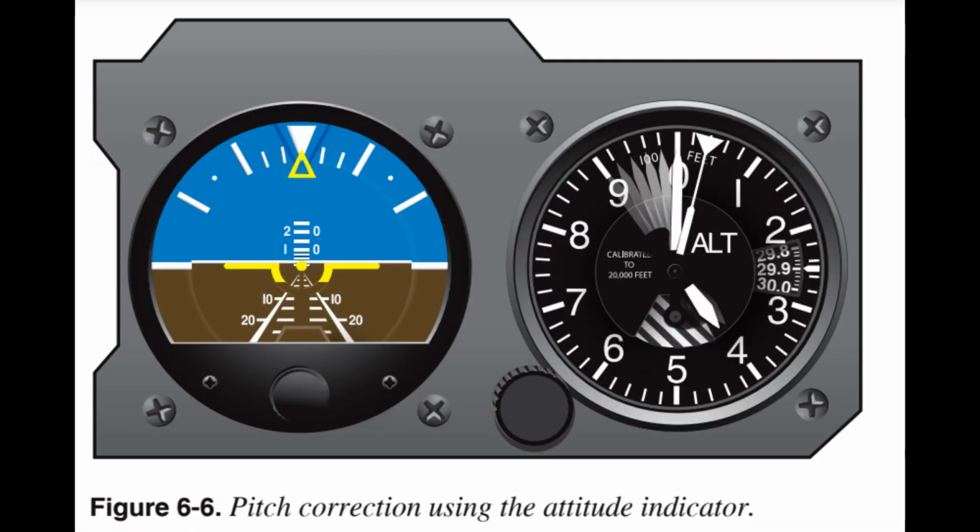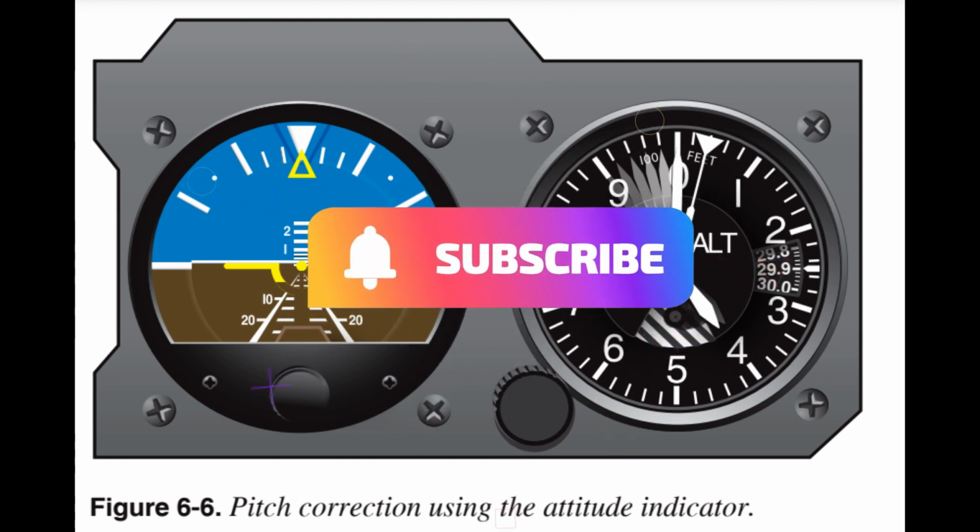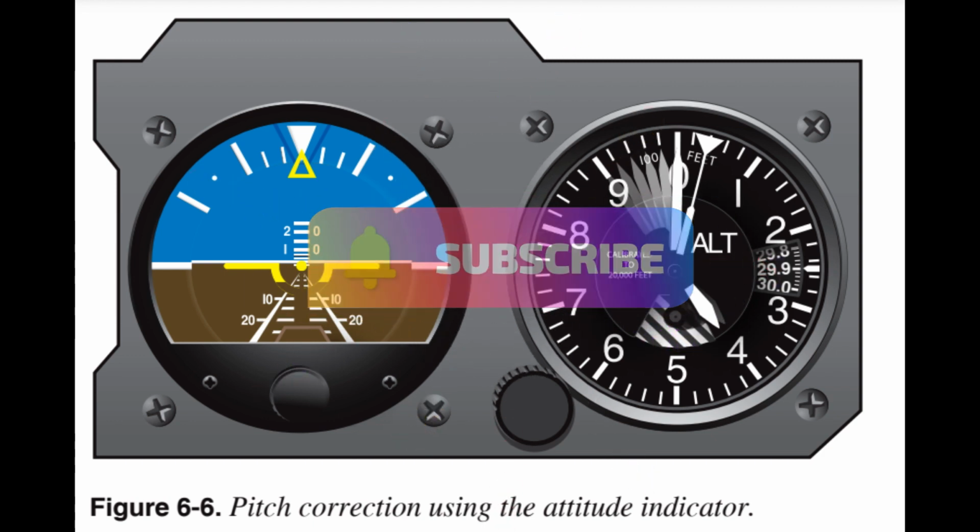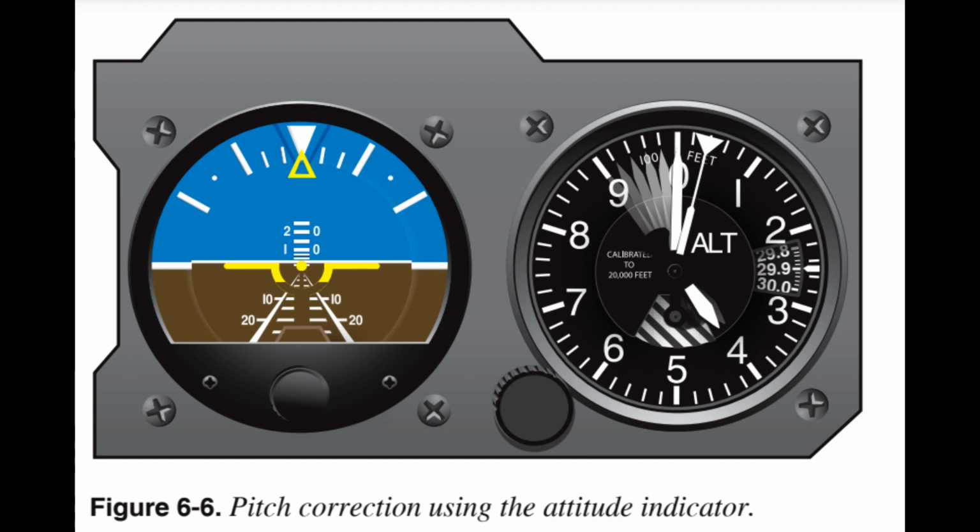When using the attitude indicator in applying pitch attitude corrections, control pressure should be extremely light. Movement of the horizon bar above or below the miniature aircraft of the attitude indicator in an airplane should not exceed 1/2 the bar width. Figure 6.6. If further change is required, an additional correction of not more than 1/2 horizon bar wide normally counteracts any deviation from normal flight. Altimeter.